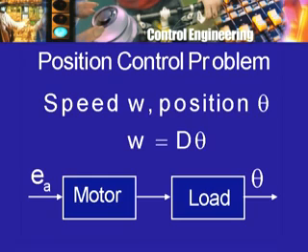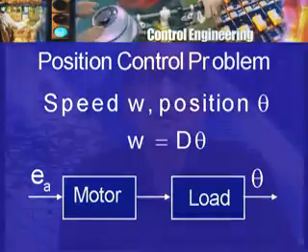For a small change in position, perhaps a small armature voltage applied for say 1 second is enough, whereas for a large change, and if you want that change to take place quickly, you may have a large voltage applied for that same duration of 1 second. The motor will make the load move through the desired angle in a shorter time. So, this is the open loop situation.